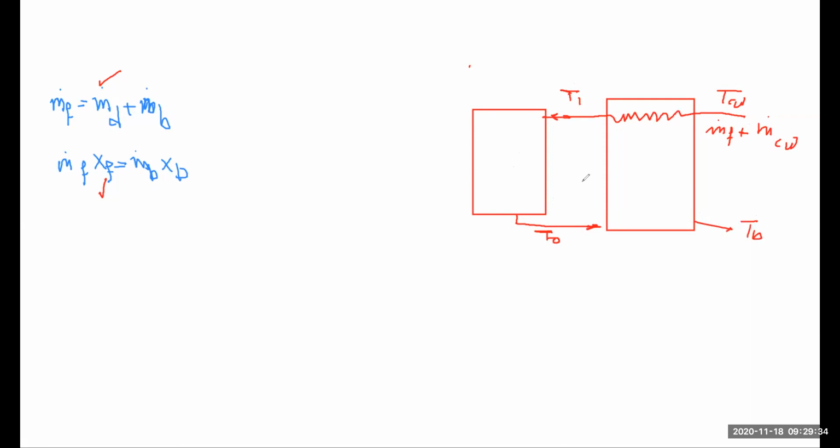What will happen inside is that vapor is going to form. It will rise up. And here we have a distillate tray, which is collecting the distillate. And there is some sort of a demister here, so that the vapor will pass by the demister so that no droplets are going to form here. It will condense here, and then it will be collected as distillate water here. And this is basically the brine pool that we have inside.